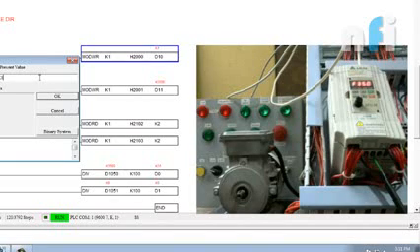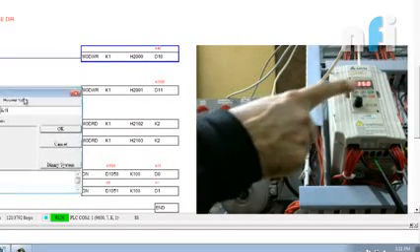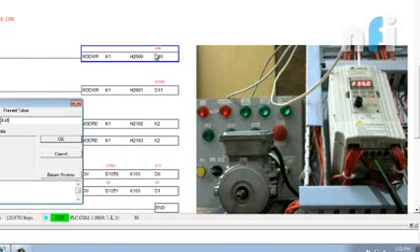Actually what happens is, if you're going to toggle the direction, you just have to give the toggle command by sending a pulse. You don't have to continuously send 48, as that will create a problem. If I put 48 here, you will see it's toggling forward, reverse, forward, reverse. Why is it happening? Because at every moment this 48 is going. When it goes to forward, a pulse comes, it goes to reverse, a pulse comes, it goes to forward. So you just have to change the toggle direction just once. Okay, so let's just avoid this right now.